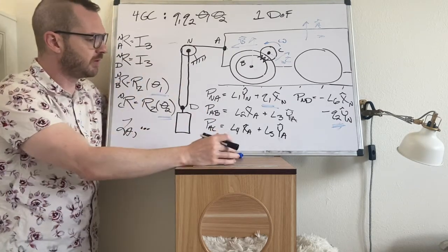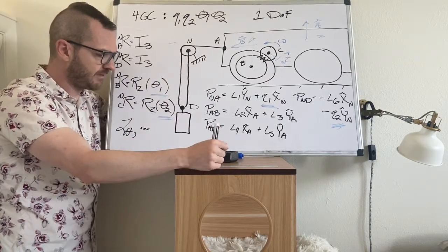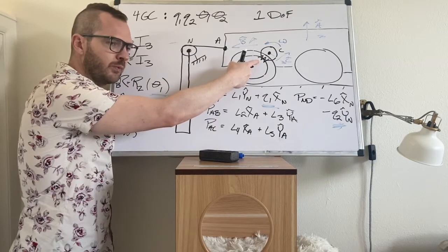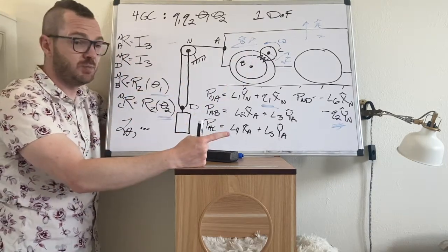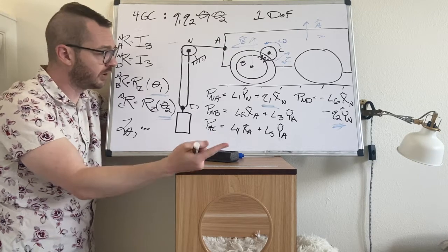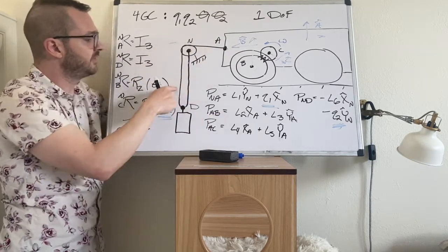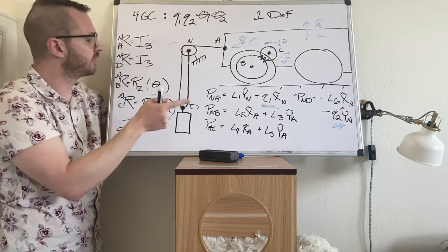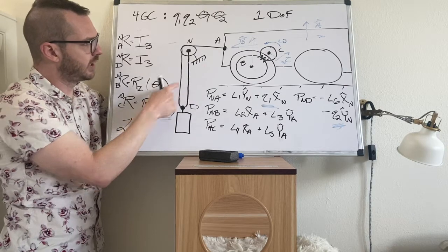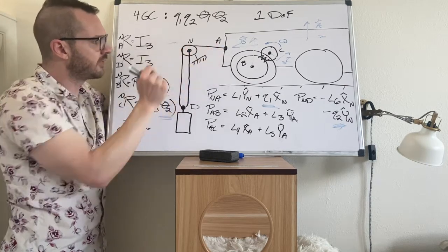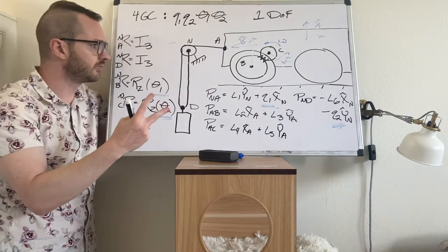We look through the problem and we just ask ourselves, does this thing have any gears? Hey, there's one gear interface, so that's 1 gear constraint. Does it have any pulleys, rope pulley systems? No. It does have a rope though, right? This isn't like a belt and pulley like we saw in the previous problem, but it is a rope, and that rope has constant length, right? There's one end of the rope, there's the other end of the rope, and we're going to assume that the rope doesn't stretch. So 2 constraints.